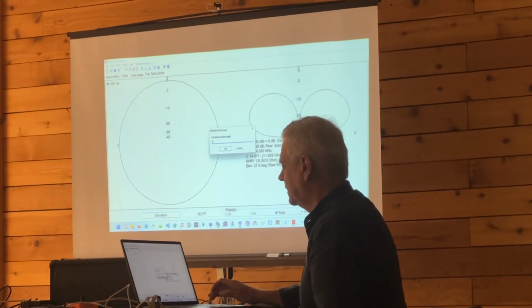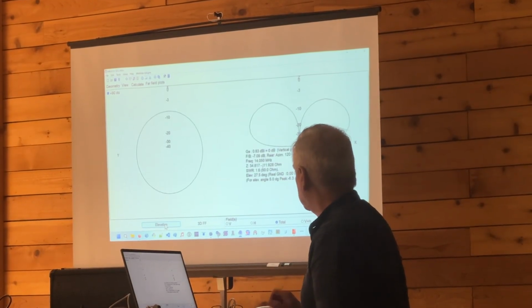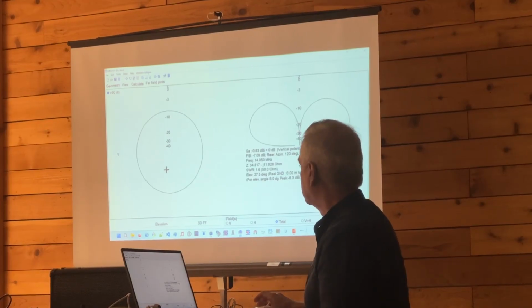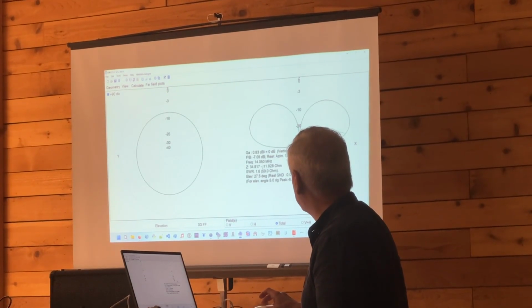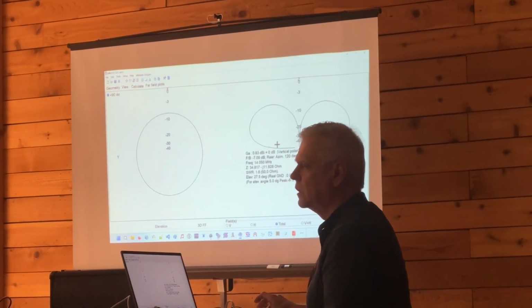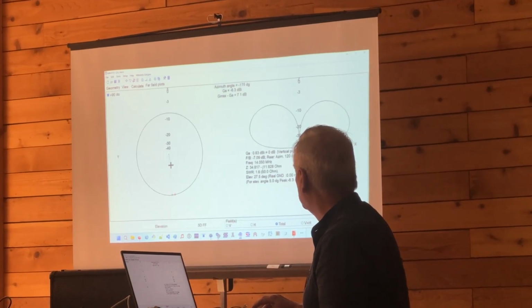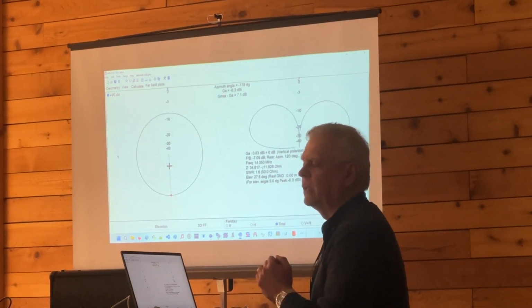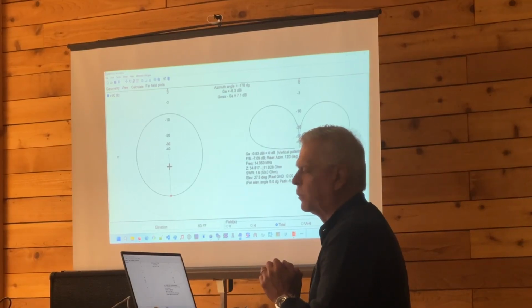And as soon as we tell the program 5 degree elevation angle, one thing has happened here. The azimuthal pattern has become smaller. Why? Because essentially what we're doing is we're taking a 5 degree cross section across this donut right here. So that is telling us, we hold the mouse down, and we see what our gain can be at this elevation.